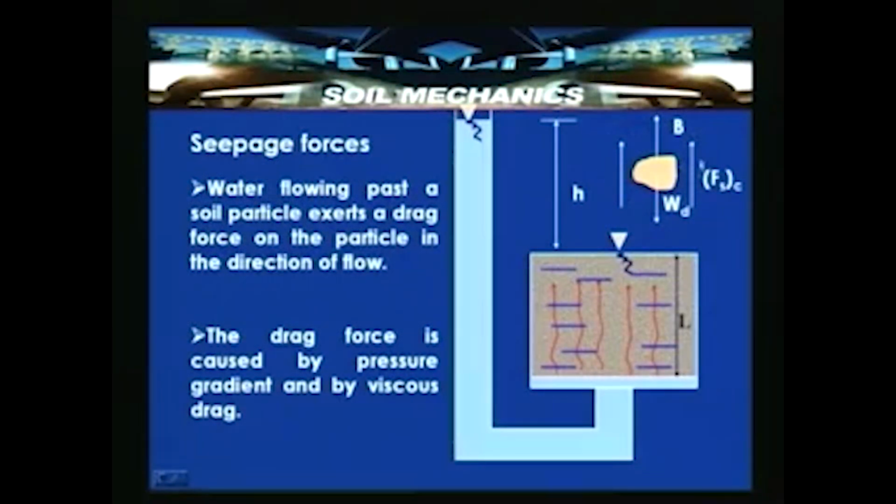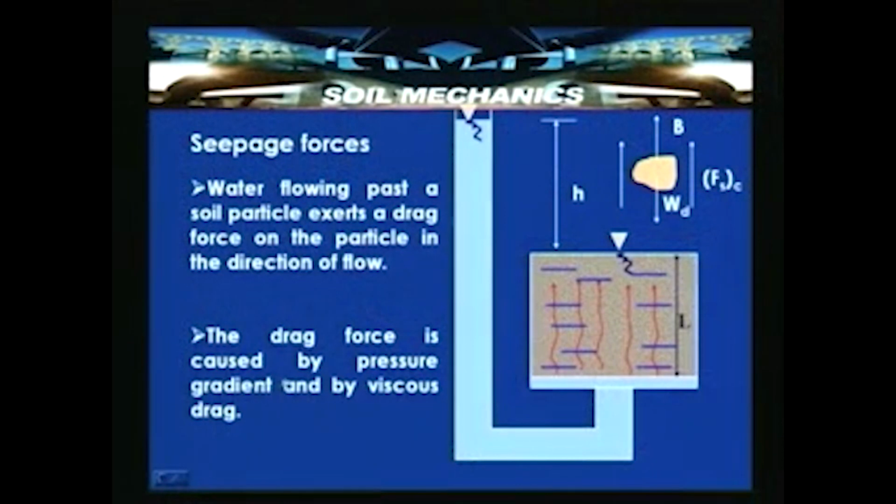So, if you consider the equilibrium, then we will be able to achieve an expression for the seepage force. The drag force is caused by the pressure gradient and viscous drag, that is what we are discussing. The drag force shown here is caused by the pressure gradient in the form of a frictional drag and by viscous drag. Water flowing past a soil particle exerts a drag force on the particle in the direction